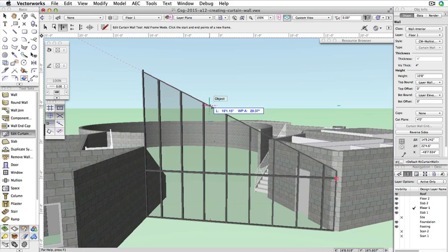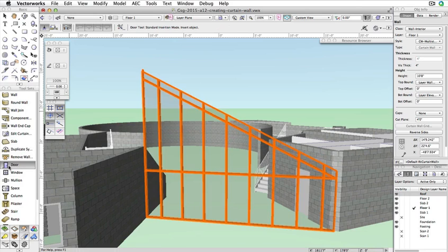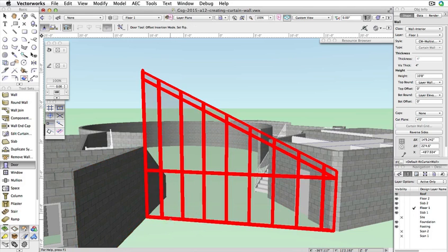Then, move your cursor down and to the left side of the curtain wall while holding the Shift key. When the cursor cue Object/Edge is displayed, click again to create the frame. Remember, we still need a door to access this entrance. Activate the Door tool in the Building Shell toolset and click the bottom midpoint of the 2nd panel from the left. Click again to place the door.